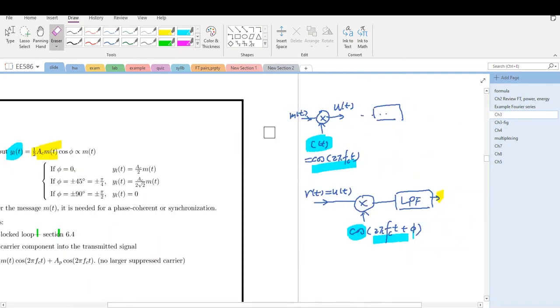In lab 4, we're going to perform the demodulation of DSBSC signals. That's this scheme. To demodulate the signal, we need to modulate first. So you're going to have a multiplier to generate the modulated signal here. Then this signal passes through another multiplier, which multiplies by a cosine signal with phase shift. This phase shifter can be adjusted by a potentiometer, but without digital reading.